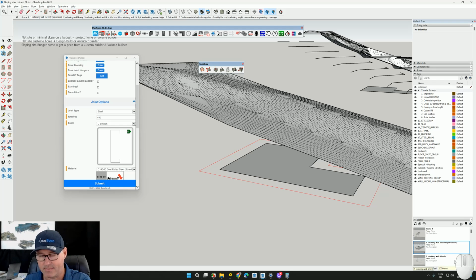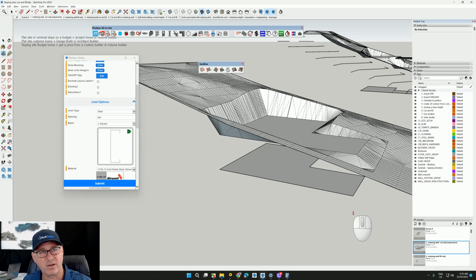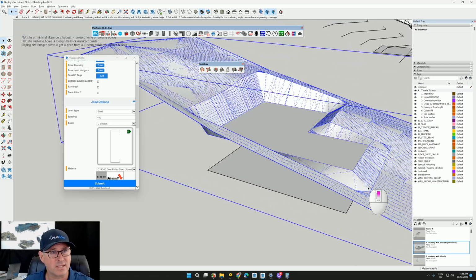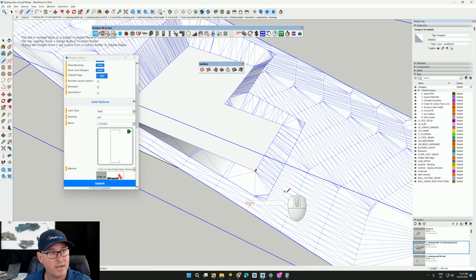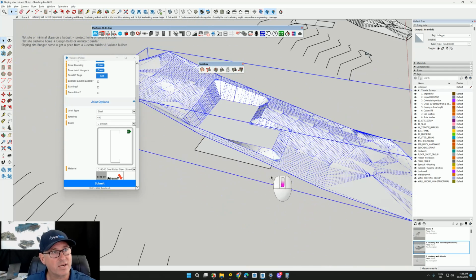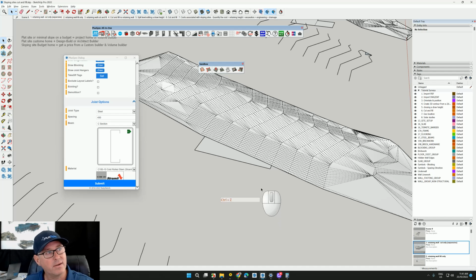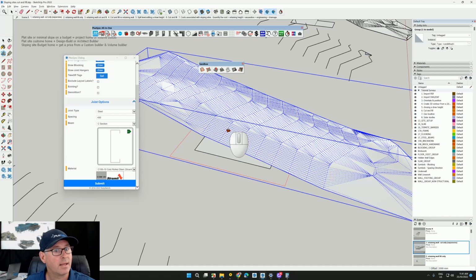and then enter. Now when I actually do that and stamp it on the project, it remembered the last thing. It's kind of a bug, I think, inside of SketchUp, but let's have a quick double check. If I go line and go out on an axis, which should be red, and go to here, you'll notice that down the bottom it still says 1 meter. To rectify that, it actually remembered what I wrote in. I'm going to go back to here and do it again. You'll notice that it's now remembered 2 meters, so I just had to do it twice.